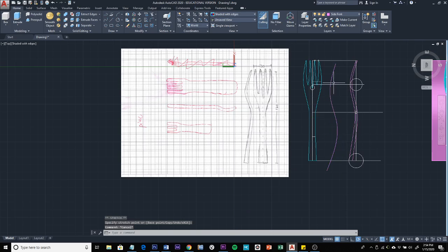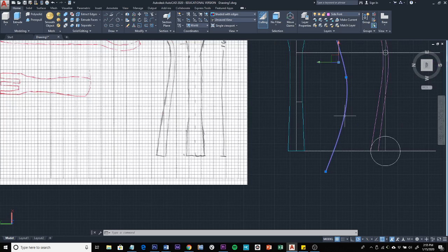But a lot of times you'll need extra points. Depending on how you drew it, you can add fit points. If I wanted to add a point between here and here, I can't click on this point because that was the last point that I drew. I can only extend or add a point this way. So I want to grab this point here, just hover over it and do add fit point. Now I have an additional fit point that I can adjust. Say I didn't want it as angled. So I click right there.